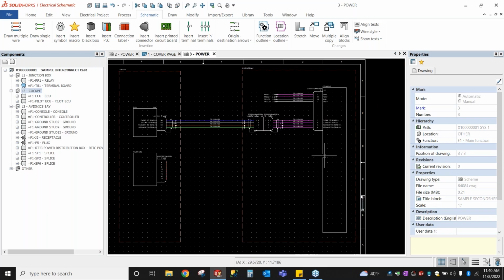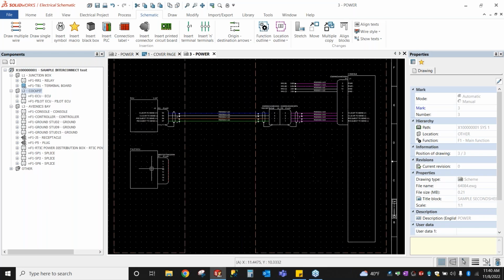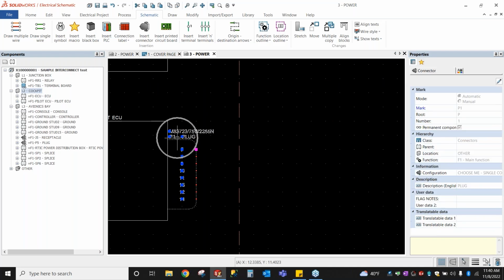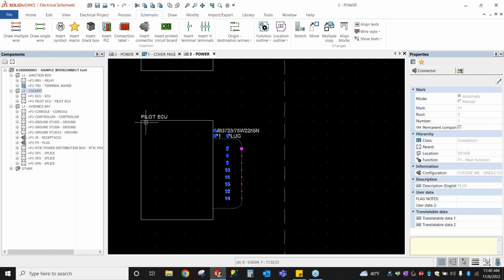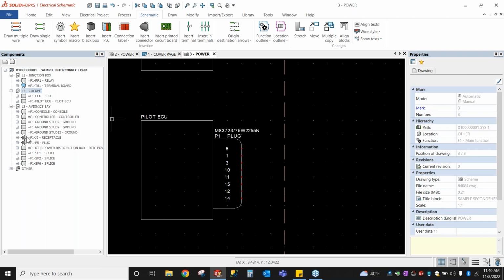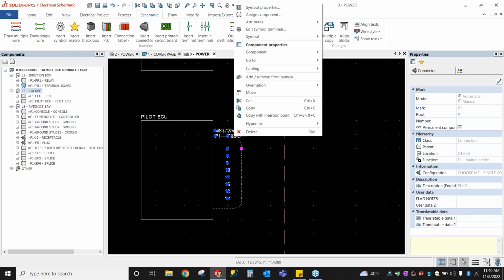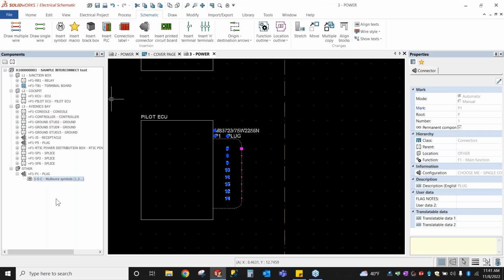Over here on this console, I'm going to add a new, oh, wait, I can't get too ahead of myself. So the way I inserted this connector part number over here is currently P1, and sometimes I'll get confused in my own list over here, and I'll wonder where this P1 is in my list. So sometimes what I do when I get too lost in my own project is right click on a symbol on the page, click go to, and go to the browser, and it'll open something up for me. So what I can see here is now this connector is down here in this other location.